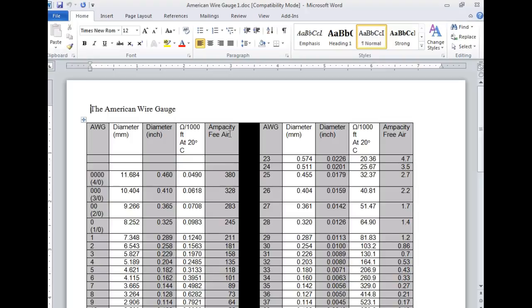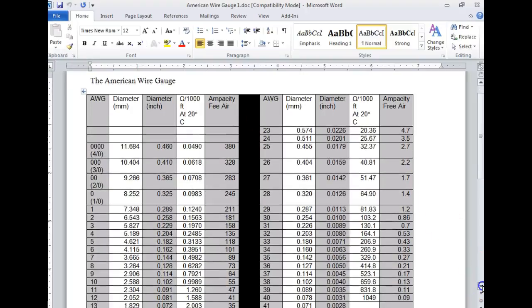But why don't they insulate them? Well, they don't insulate them because if they insulate them, the ampacity, the current carrying capability of all those conductors would go down. So they would have to use bigger wire gauges just to insulate them, which would cost the power company so much money. So they just put them up high enough so only idiots can climb up there and get into them.